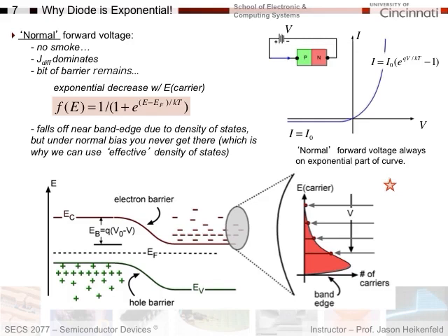So, here is my distribution of my concentration of carriers versus increasing energy. And I kind of drew this pictorially here, meaning I have few near the edge. It increases near a maximum a little bit above the conduction band here. So this is the edge of the conduction band. And as I go to higher energies, I get exponentially less and less. So with no voltage, these carriers here are the only ones that could diffuse from high concentration to low over this energy barrier, right?